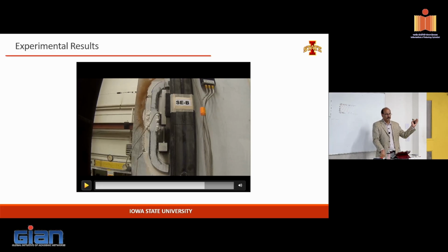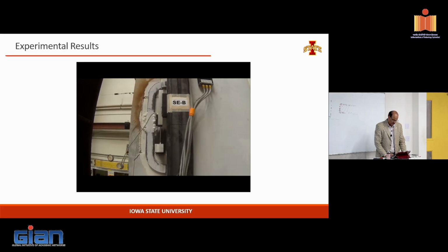So first one, unbonded post-tensioning, no damping. It is rocking quite a bit. Second one is a pre-wreck system with the energy dissipation. The important thing to notice is that the wall is not rocking as fast as before once energy dissipation kicks in. So it has also altered the impact damping associated with that second system, because you put in energy dissipation here. So the energy dissipation is taking place through here. That's what you're seeing in this particular video.